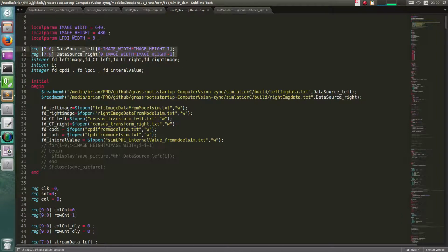You have to use block RAM, or a distributed RAM, which is made of a special kind of lookup table. Both Xilinx and Altera have such lookup table resources, I guess.